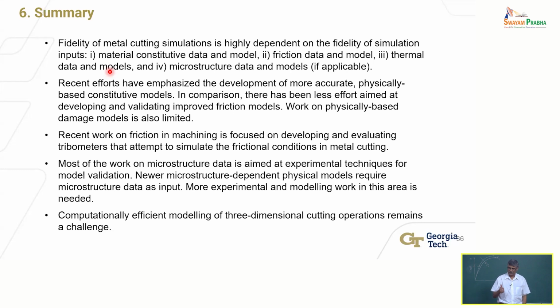Predicting tool life is not easy, even now. Many of these software packages have several tens of materials, tool material properties and workpiece material properties. But if you're trying to machine something very different, then you have to build all these constitutive models and incorporate them yourself. Those are required before you can use these simulation tools. So there's still quite a bit of work to be done to bring this technology to the point where it's practically useful.